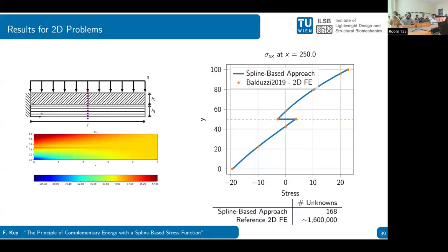Say, for example, with the same number of bases, the same setting for the approximation, if you consider different materials, or the same setting but the same material, are there differences in the decaying convergence with respect to the number of bases? I wouldn't expect a difference there, because basically I have two phi here, and they are basically independent except for the coupling conditions. But the coupling condition doesn't lead to any condition on the sigma xx. Therefore, it can also have the jump.